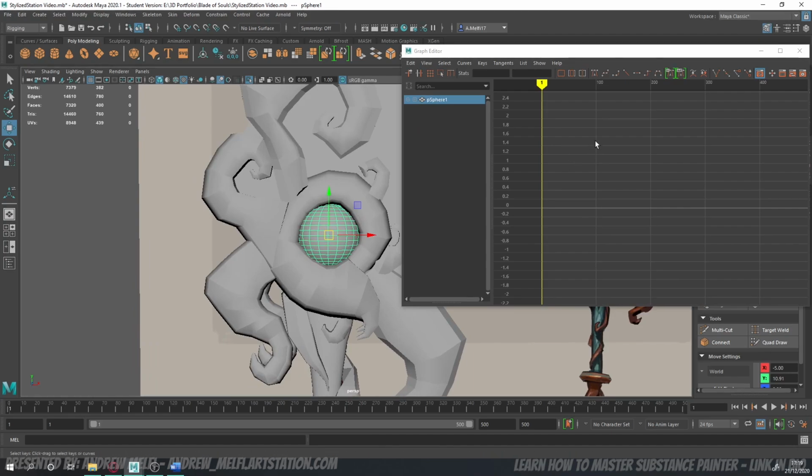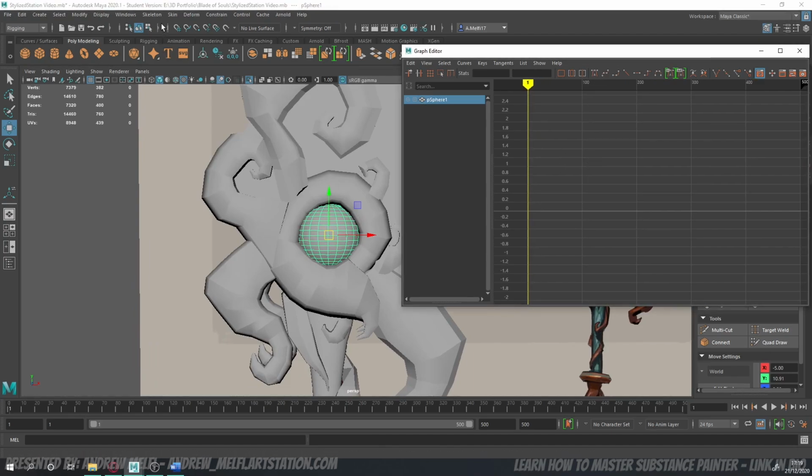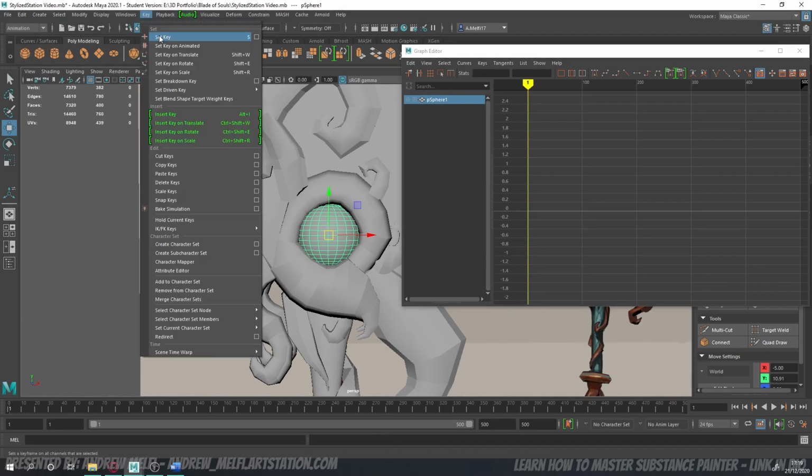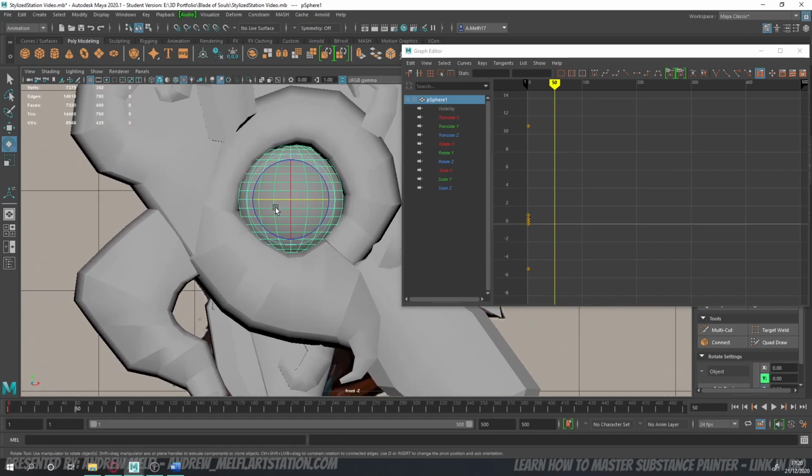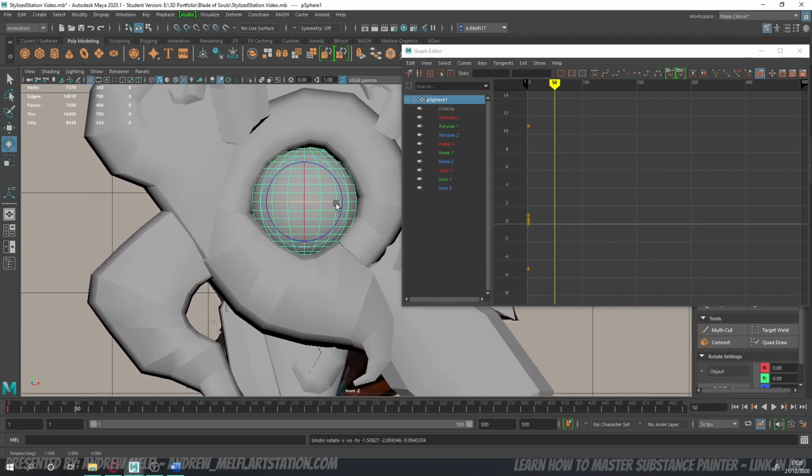So to start with the keyframe animation, what I need to do is go to animation, key, and set the key. This is basically the first step of the animation that we're going to do. If we key this in, this will put the little dots on the animation screen. I usually try and do whole numbers with this. So if we drag this over to 50, go to the front view, it might make it easier. If we just change the position of the eye, so we have it looking up to the left to start with,